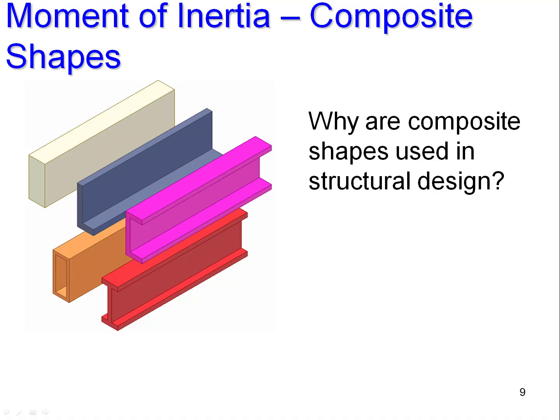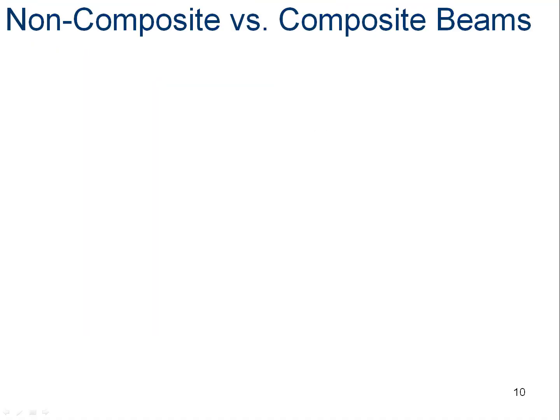There's reasons that we want an I-beam, the flange is what that's called, to attach things to. Also because we don't have forces in just one direction. We have forces in many directions. We have wind loads, seismic loads, all sorts of different loads that we have to counter using different orientations of the I-beam. But the predominant force is down.